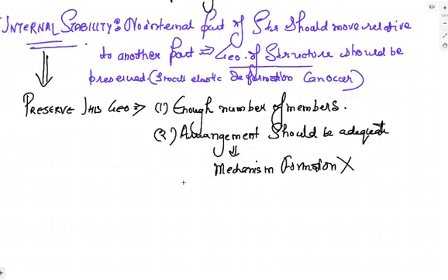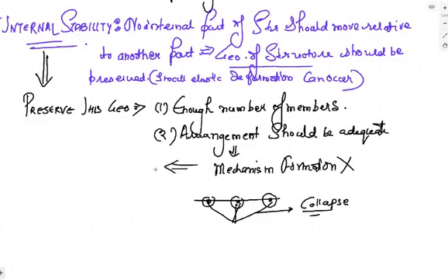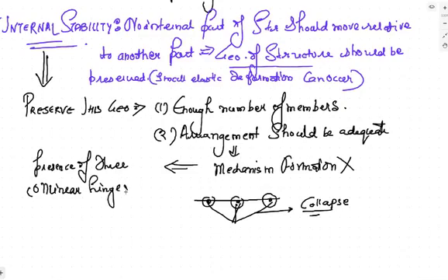Mechanism formation should not be present. Mechanism formation का मतलब होता है continuously the presence of 3 collinear hinges. For example, if a structure is like this, and in this structure there is a hinge here, a hinge here, and a hinge here, because of these 3 collinear hinges, the structure will collapse like this. This is known as collapse, which is due to the presence of mechanism. And what is mechanism? Mechanism is the presence of 3 collinear hinges, जो मैंने सो में भी बताया. Presence of 3 collinear hinges together will lead to the formation of mechanism which can directly lead to the collapse of the structure.